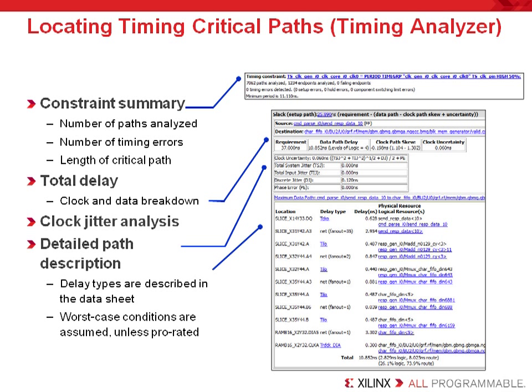Too many logic levels might be the problem here. But there's lots of different possible problems, including your net delay, needing logic duplication, etc., that can be part of the problem. But the beautiful thing, of course, is the marvelous detail. And again, this is all for worst case operating conditions for each of your data paths.